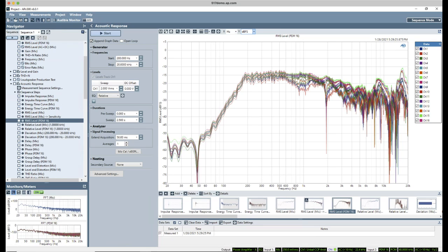Typically the way a mic seal test is done, or the most common way that I'm familiar with, is you measure the frequency response of your mic, and then you occlude or cover the port for the microphone. If the cavity is well sealed from the rest of the device, that occluded port should cause the frequency response to be severely attenuated, maybe down to 0 or near 0.